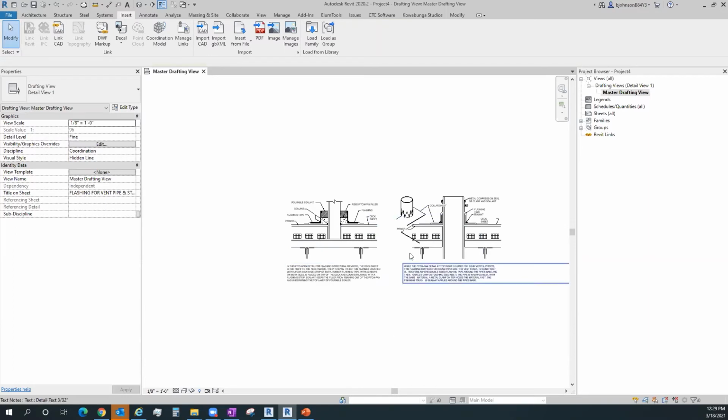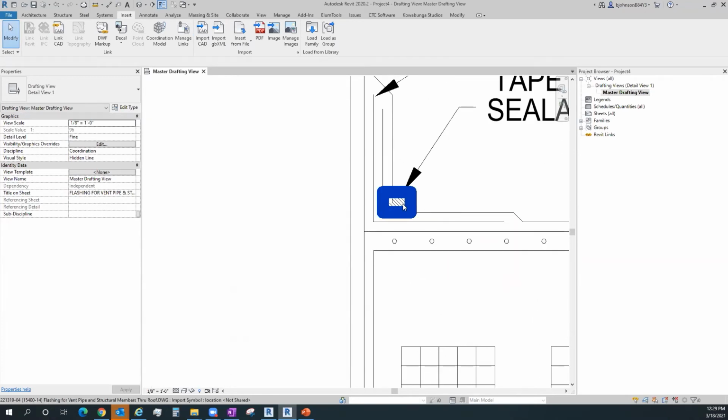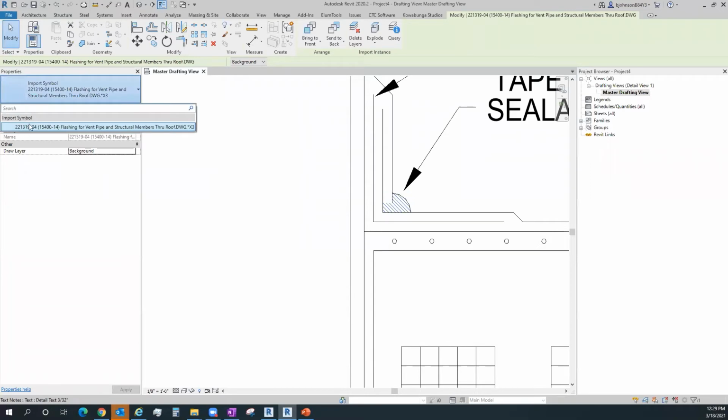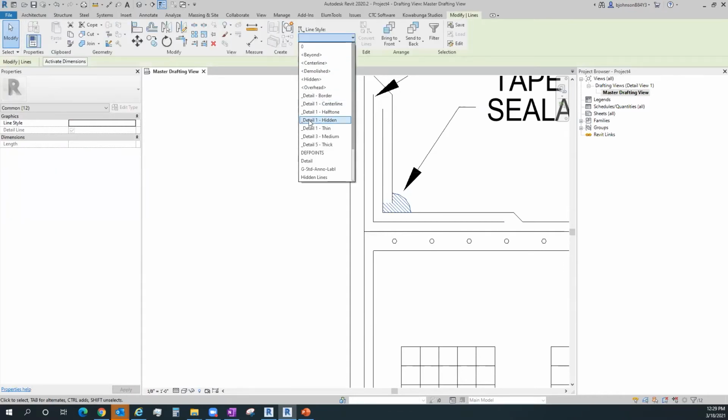So you can kind of see that takes a bit of time, right? It's probably about a 10-minute process to do the majority of all that cleaning. Really depends on the amount of entities that are actually in there. Do I have more things that are not going well? Like here, I still have a fill pattern of those lines. So if I had a diagonal ANSI 45 or something like that fill pattern that I could change out to, I don't have that symbol in here right now because I started from that none template. So I'd have to bring those things in, or I could go back in and explode each of these extra fill patterns and then have new line work that I need to go back and change to my, say, thin line again.